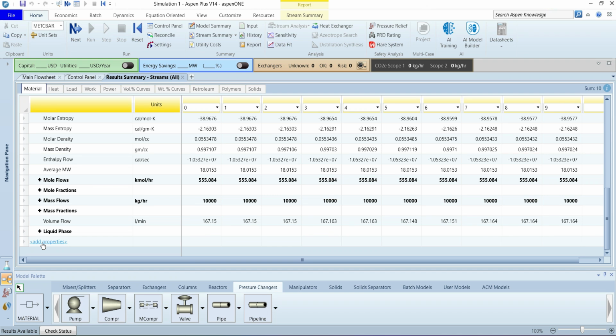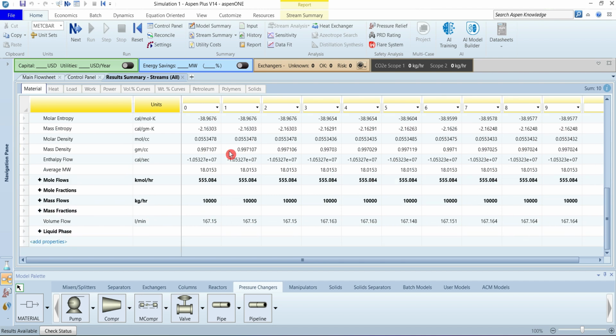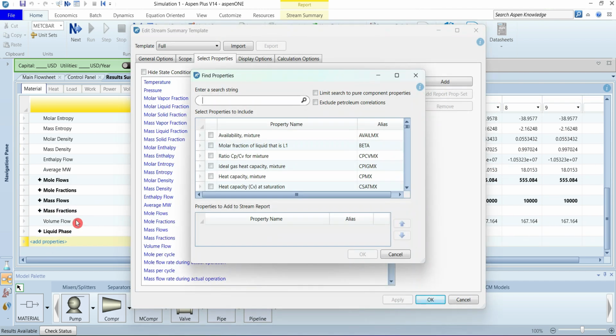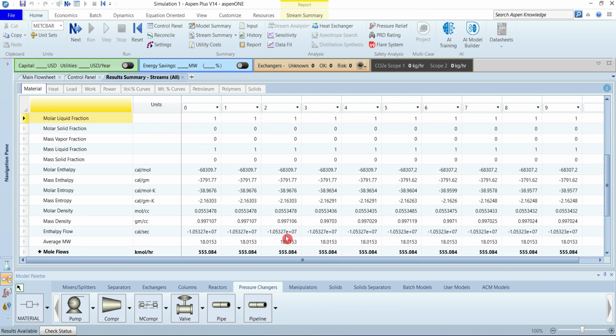One property that would be very relevant in this exercise is the vapor pressure. If the vapor pressure approaches the pressure of the pipe, that is an indication of where cavitation can form, or bubbles can form, leading to vapor formation from the liquid phase. Though apparently we are not expecting any cavitation in this case, it's still good to have the vapor pressure of all the streams labeled over here. You can call the liquid vapor pressure. The alias is PL for this case. Let's add it to the existing stream table and display the result at the bottom.